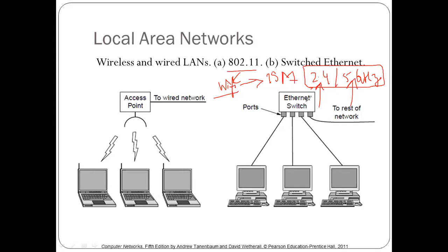Now for improving the connectivity, when it is using 5 gigahertz, nowadays you will find that the device has two antennas, right? That is basically to increase the coverage area. As we know, 5 gigahertz will not be able to reach as far as 2.4 gigahertz. So to improve that, what companies are doing is this: 5 gigahertz will increase the data rate, but how can we increase the coverage area? For that they are providing more antennas so that it can reach the maximum range, right? So that was the point.